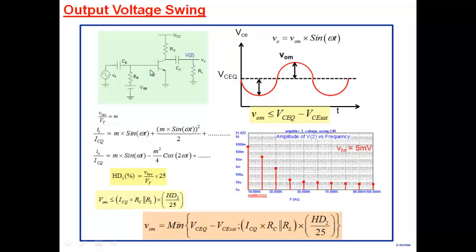The other thing is, very often we forget, we keep hearing small signal, and we tend to think that everything has to be small signal, in the sense that every voltage has to be small signal. Note that small signal only means the base emitter voltage is smaller than VT. It does not say that the voltage here at this node has to be small. The voltage at this particular node can be a volt, 1 volt sinusoid, 2 volt sinusoid. That's not where the issue of small signal comes in. Small signal comes in only at the base emitter part. Okay, voltages here can be very large.